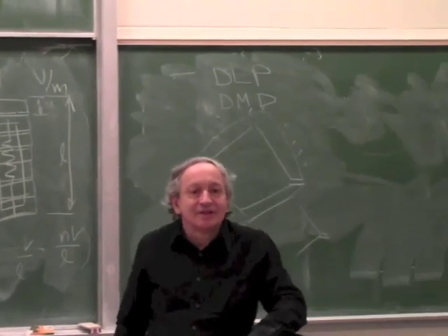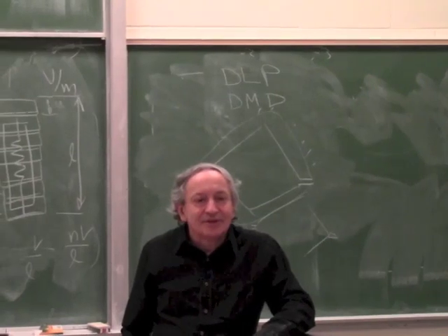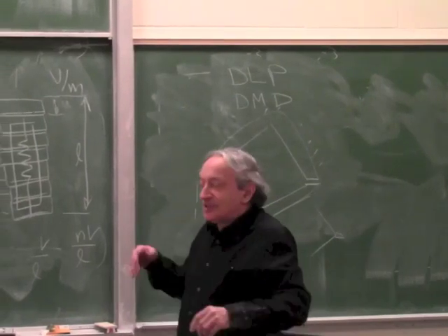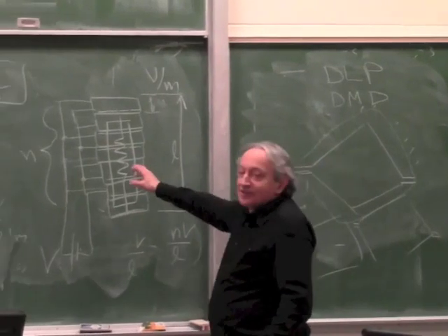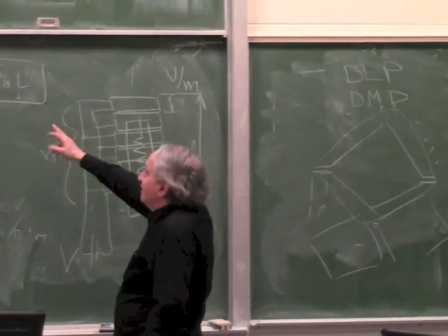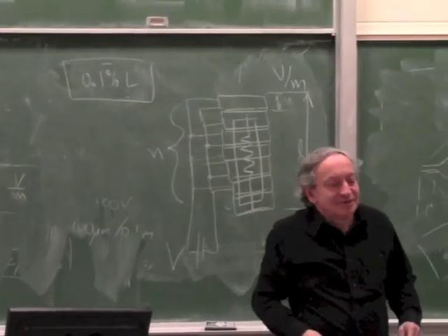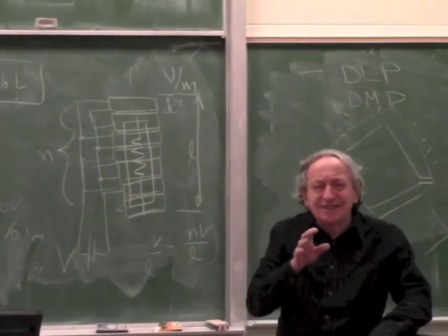Yes? Using that stack actuator with the strain gauge, what's the maximum accuracy? Like, what's your limiter? Accuracy is pretty good because now it's a servo. The strain gauge measures, so the accuracy should be as good as the strain gauge can measure, but you're still limited to that. That's really the problem. You still get very small motions. And there are other subtleties.